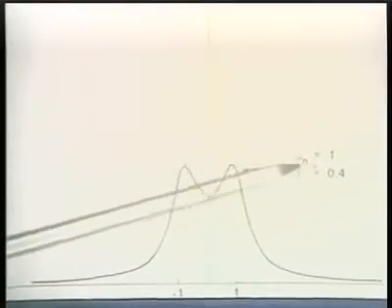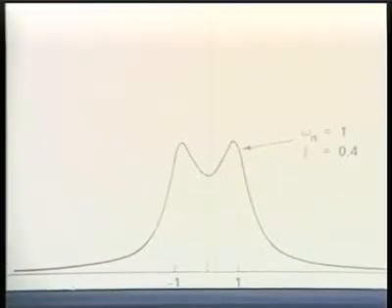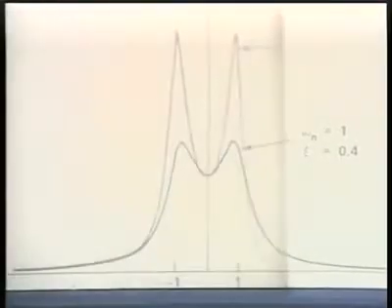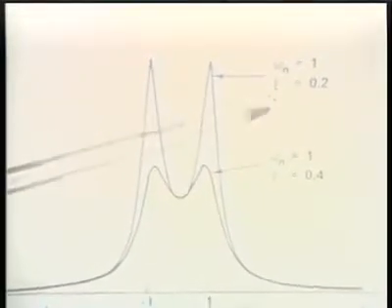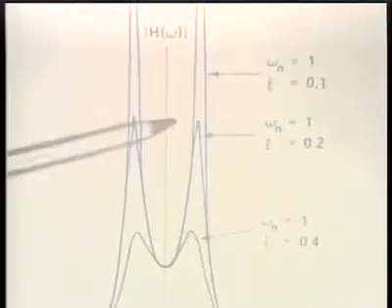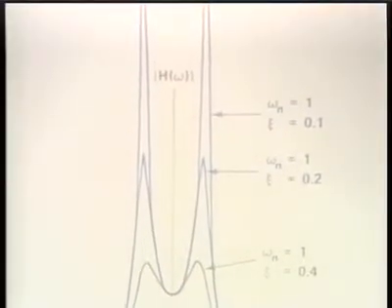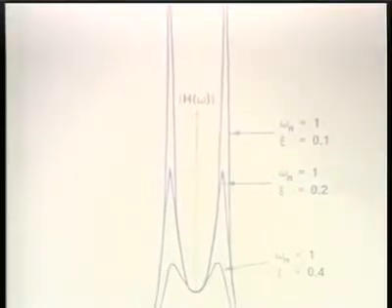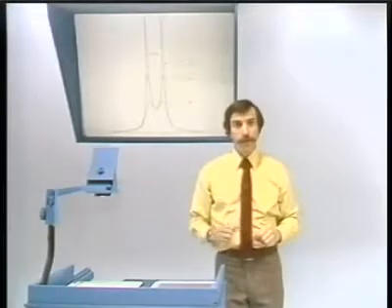Well, this is normalized so that omega sub n is 1, one particular choice for zeta, namely 0.4. Here is what we have with zeta smaller. And finally, here is an example where zeta has gotten even smaller than that. And what that corresponds to is the poles moving closer to the j omega axis, the corresponding frequency response getting peakier.